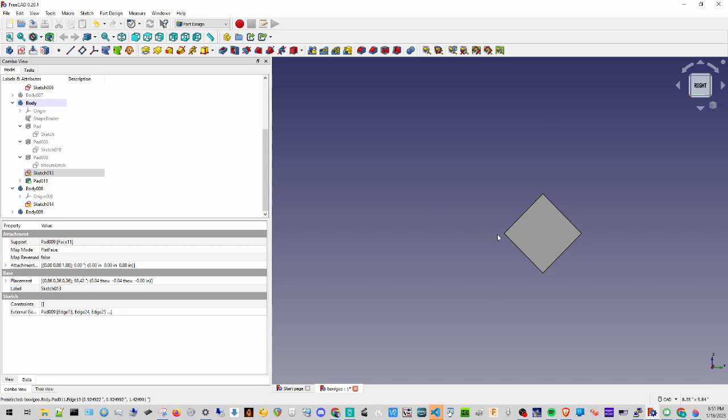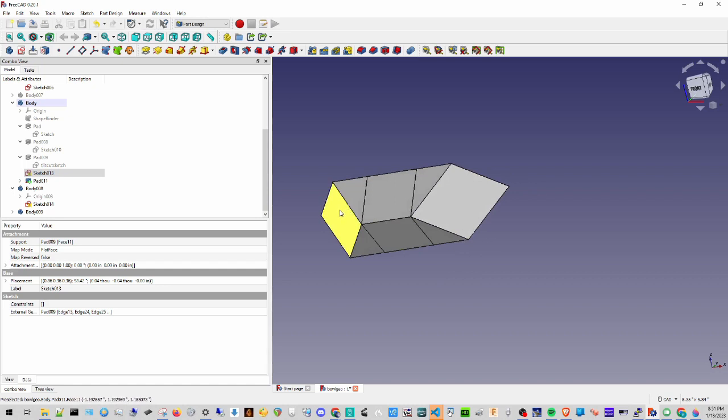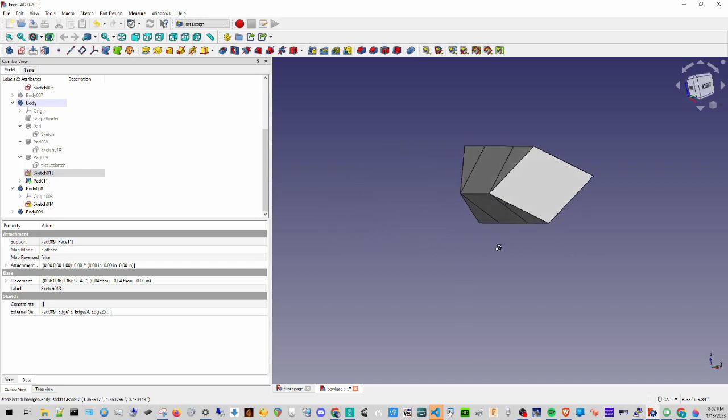That's what it looks like from the side, and the flat part of our bowl is here, and this is the petal folding out, and this is the thickness of the material. Okay, and as I move it along in space, you see that you get this face that looks like a trapezoid, which you already know by looking at any completed polygonal bowl. And we also get a trapezoid along this flat side here that's going to make contact with the bottom of our bowl. This is the piece on both sides that's going to touch the stave right next to it, and interface with it and perfectly seal things up with no gaps. And you notice it's got this diamond-ish shape.